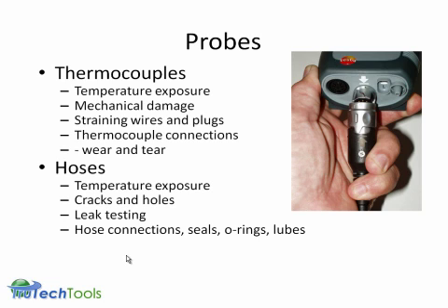When you do get it calibrated, we do a leak test on it to make sure that you're not pulling any oxygen from the ambient air. Periodically you just want to visually inspect those connection seals and O-rings, and make sure they're in good shape. You can apply a tiny bit of silicone grease to the rubber seats on the probe connections. Just a tiny little dab to keep that connection tight.